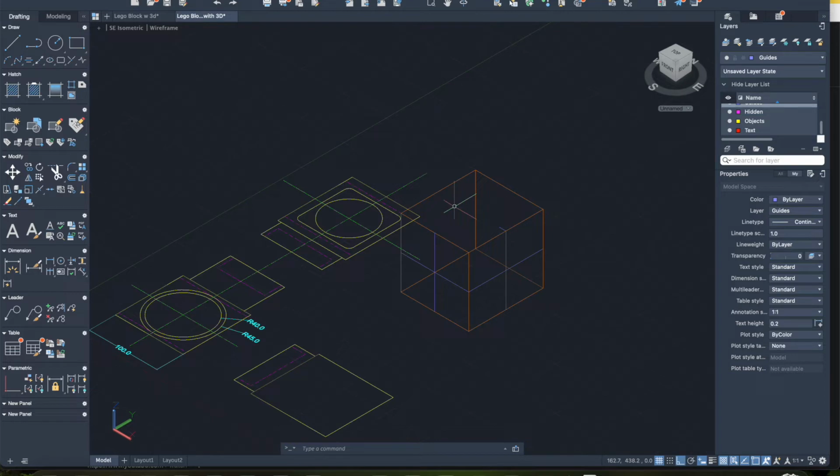Now we can add the circle that you see on the right side view, okay? So we go up to here, we grab the circle tool, and we click in the center. You're going to see something that happens. It might not happen on the PC, it always happens on the Mac. So I click here, and I type in 45, and I hit enter. So my circle is in the wrong plane, and I need to correct that.